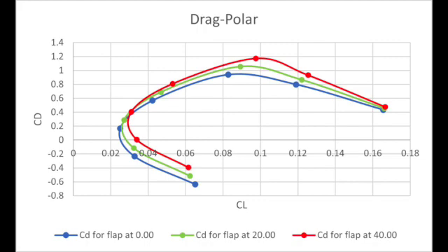The drag polar of the UAV is also investigated. The trade-off between the lift and drag is therefore provided where the best lift coefficient of 1.66 happens with a drag coefficient of 0.45 with the same flap settings as before.